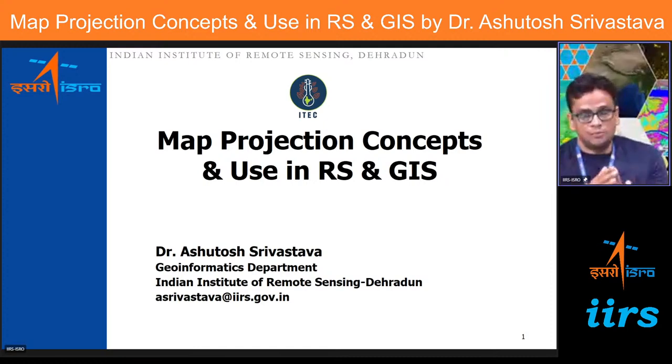Only then, when we perform GIS analysis, will it be correct. If one layer has a different coordinate system from another, the analysis you do may not give the correct answers. So better to make it a uniform projection system or coordinate system, then only your analysis is going to be correct. If it is not, you can easily transform from one to another.